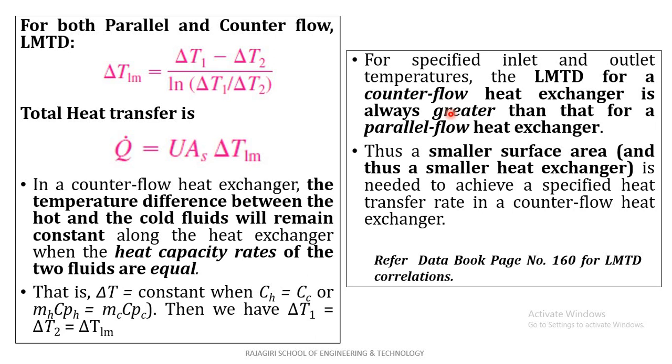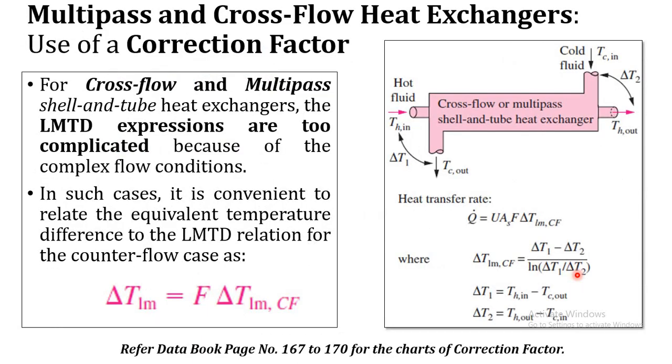Okay. So you can find LMTD correlations for counterflow, parallel flow, and also for crossflow heat exchangers from the data book, page number 160. Okay. Now let's take the cases of a multipass shell and tube heat exchanger or a crossflow.